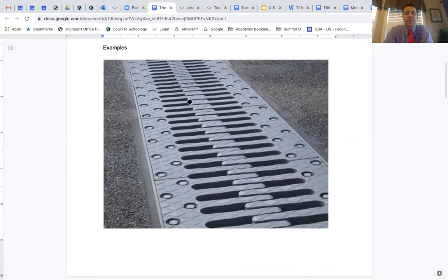This right here, this picture, is actually finger joints on an expansion joint on a bridge. This is not the only type of thermal expansion joint on a bridge. I've seen others, but what you've got is these fingers that slide back and forth as temperature changes. And so as things get hotter, the bridge portions actually will extend, and so those fingers will push closer to each other. And then as things get colder, the materials shrink and those finger joints will slip further apart. And there's a support system underneath those joints, but it allows the deck of the bridge to expand and